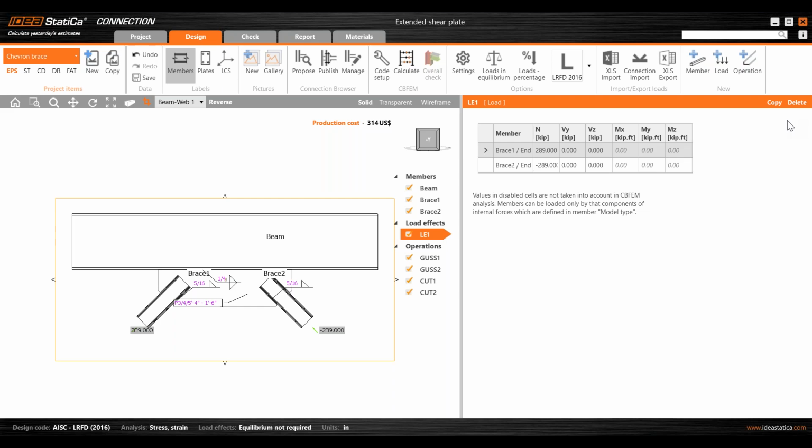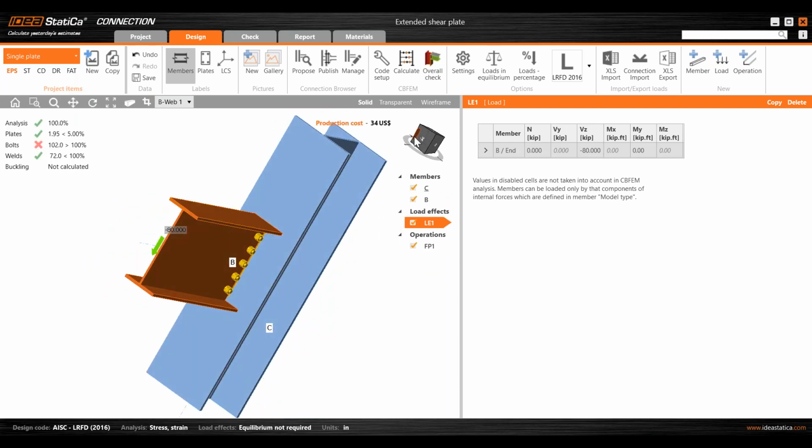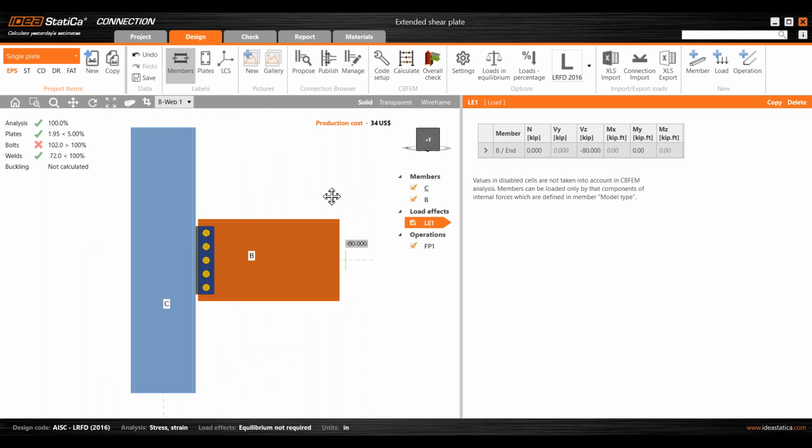And so there's a last question that came in. This is a follow-up on the question regarding shear and moments working together. If I move the point of application to have zero eccentricity moment at my connection, and the member is falling away from the connection, is there a workaround for this? I'm not sure why that would fail, apart from if the member is overstressed.